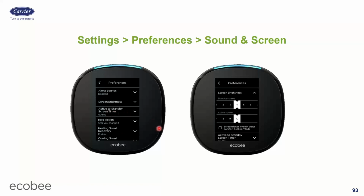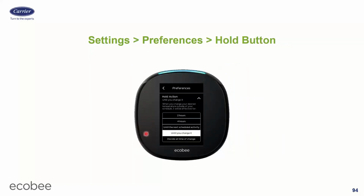Standby timer, that's just after 60 seconds or whatever you say, it'll drop down from active down to standby brightness. No big deal there. The hold action button is important. Every time the customer overrides something, meaning they raise the heating set point or the cooling set point, or they turn the fan mode or whatever manually from the stat and make it stop following its schedule, the stat is going to do that for a certain amount of time, then it's going to revert back to the schedule. Some customers don't want a schedule, and they want to just walk up like they did with their old stat and bump it to a certain set point and leave it there for days and weeks indefinitely. And I don't know why they bought an Ecobee in that case. That doesn't make any sense to me, but that's what they want to do. Fine.